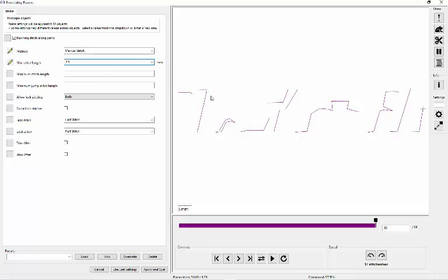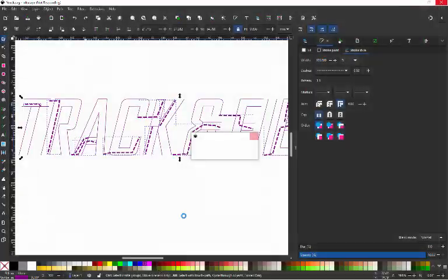But if the distance is more than 2.5, then it won't have a stitch longer than 2.5, unless it goes against what we had already clicked on. So it's kind of weird to say maximum stitch length of 2.5 because that's not entirely true, because this right here is less than 2.5, but it will respect that because it's under manual stitch. Just kind of a weird little anomaly. But anyhow, let's go ahead and choose apply and quit.